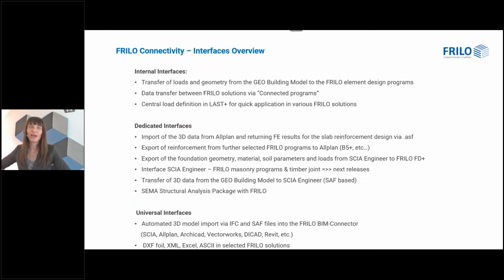In particular, we have the possibility of import of the 3D data from Allplan and return in finite element results for the slab reinforcement design. It's very easy: the AS values that are the result of the calculation of the PLT program in FRILO can be transferred via this direct interface to Allplan, and in Allplan you can make the design of your reinforcement based on that. There are also further programs that are connected to Allplan, for example, B5 Plus, reinforced concrete column.